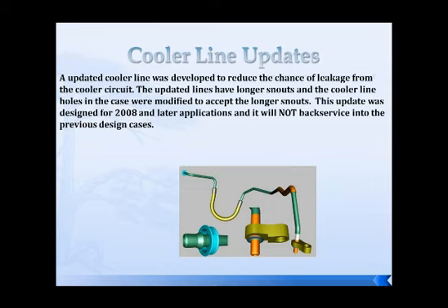Cooler line updates. The cooler lines were changed in 2008. This change was because they were having concerns with leakage of the cooler lines themselves. So what they basically did was they changed the bore in the case where the cooler line goes. That's the reason the new updated cooler lines will not back service.